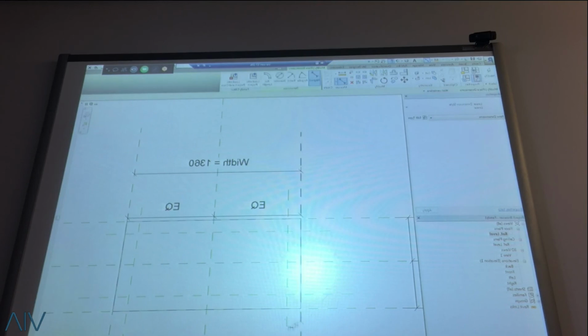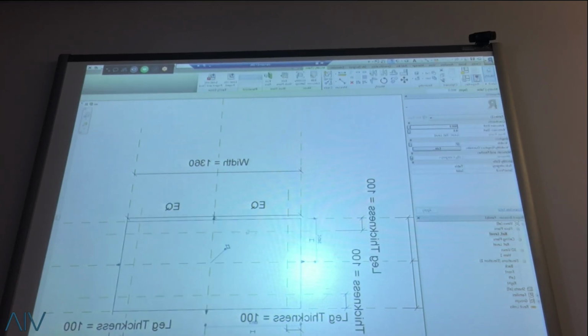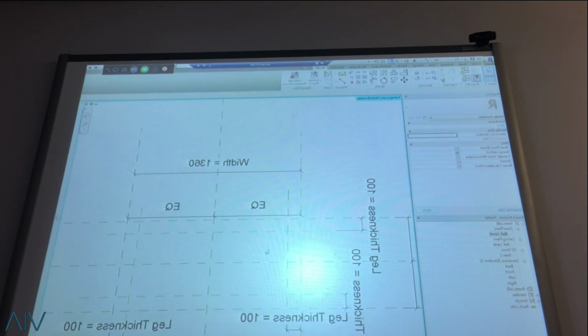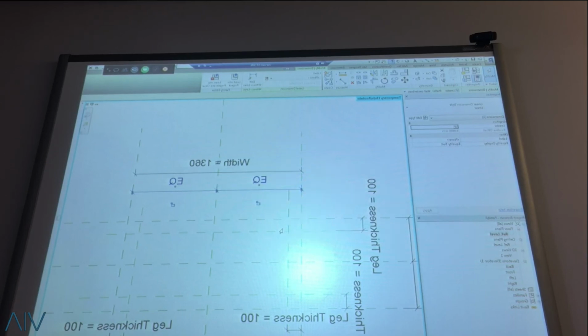And next I'm gonna just say, add that in, add that in, and then select that and say leg thickness. Okay. Now the next thing you want to do is that you want objects to not interfere with other objects. So it's always a good idea to turn off the original objects so that you only get the frame. It's a good practice because whenever you select objects and you have another object interfering, sometimes it will not click onto it.